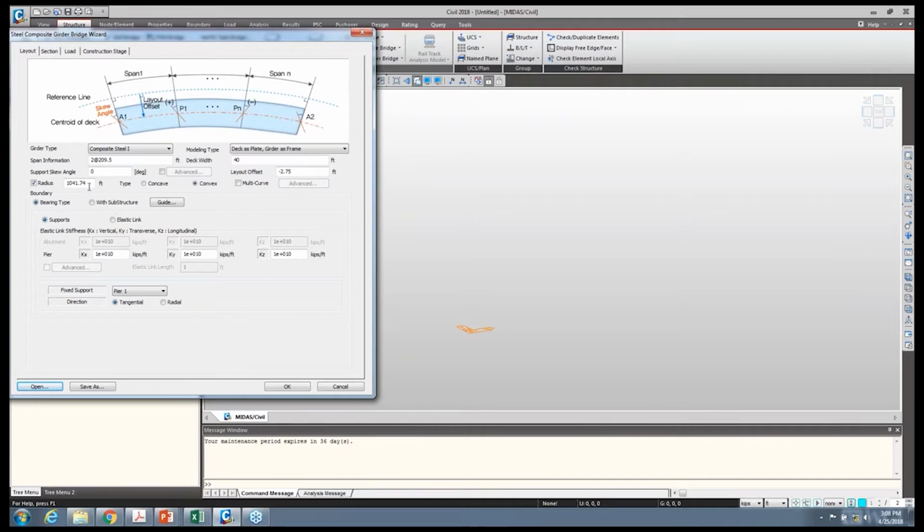One thing I also like to mention, and I actually like to do this as a trick to myself, is always make sure to be in the right units right here in the bottom right-hand corner. You can change these units to be standardized every time you open up the project to make sure that they go to the correct units that you're familiar with working with. And right there, as you see, I was working on something recently in metric units.